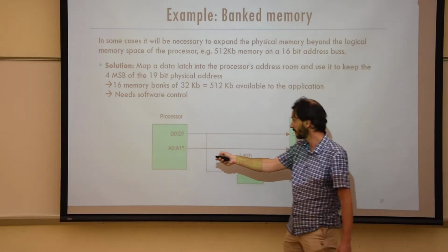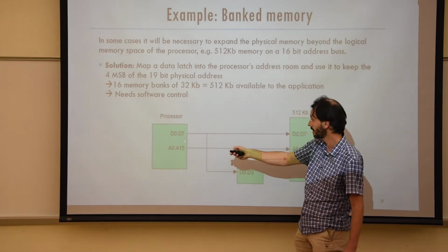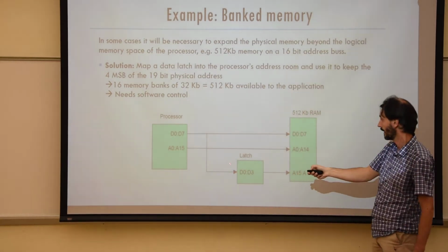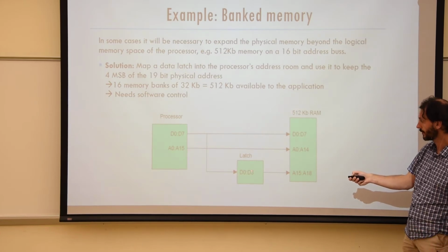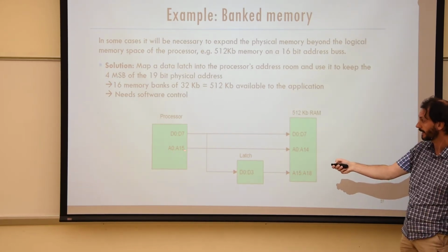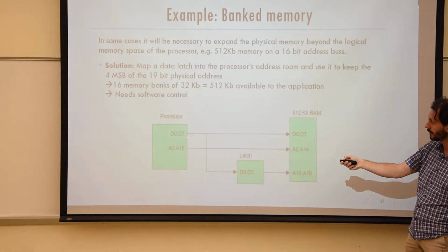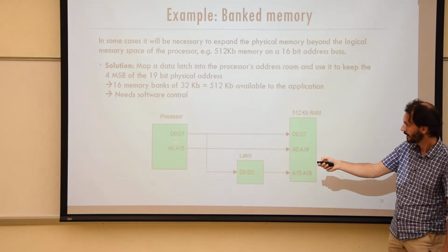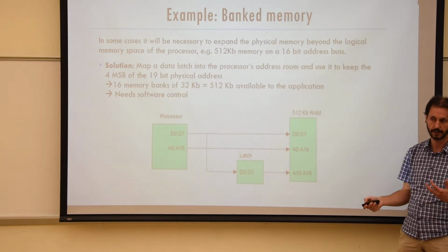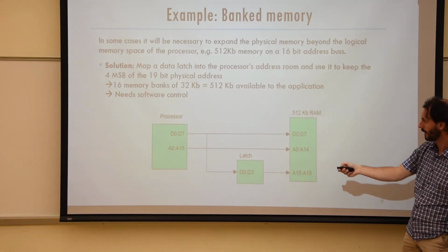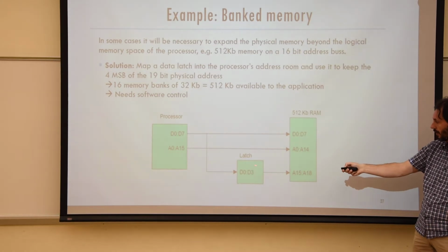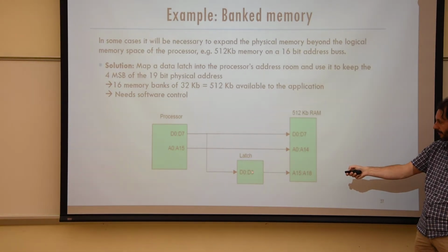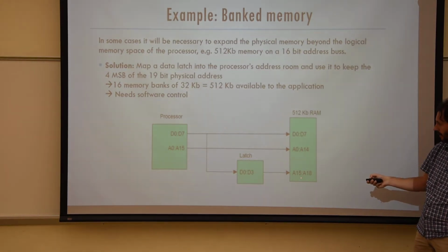But the point here is that we will have, again, address bits, data bits, and because we really need 19 address bits, we're going to use these data bits, and we essentially multiplex those in a way that they can also give another bunch of address bits, like our, oh that's wrong, A16, A17 and A19.